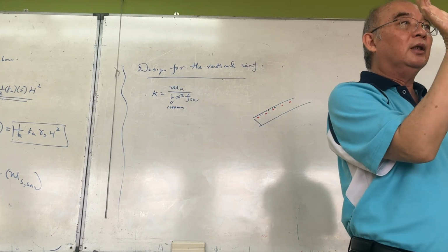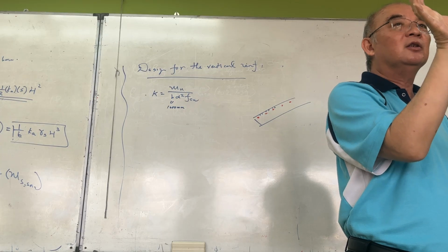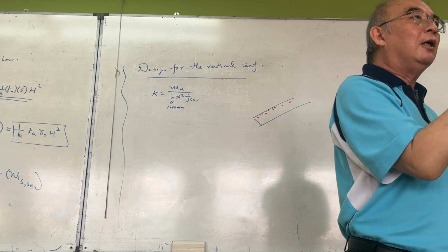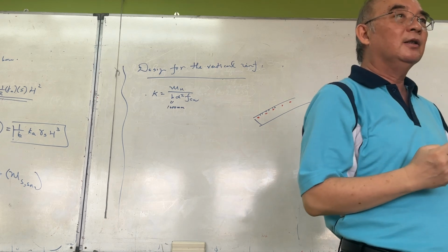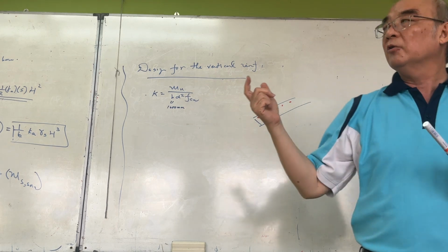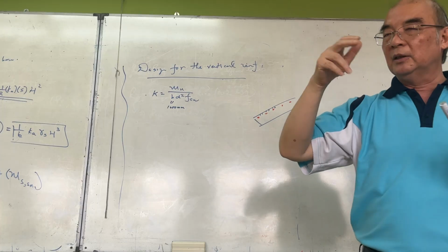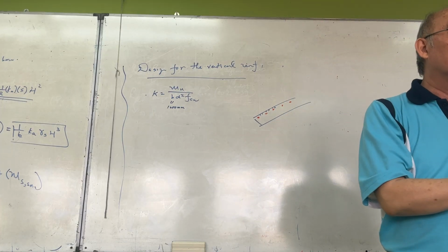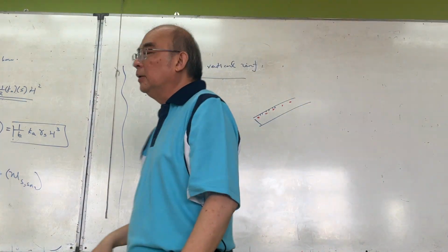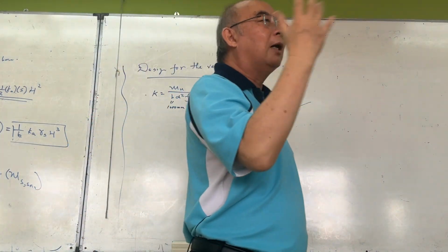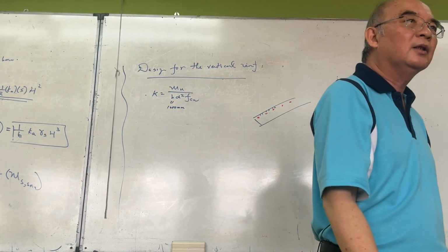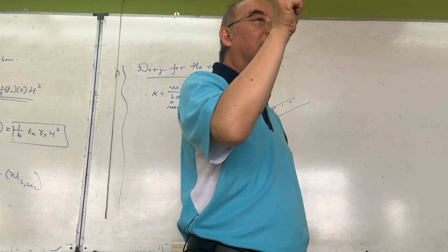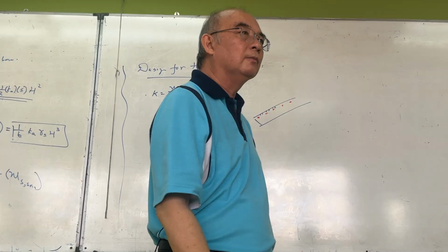TW is the total thickness. So effective thickness is the total thickness minus the concrete cover, because that concrete cover is not effective. Understand? Alright, let's say the concrete cover is 40 plus the bar diameter, but normally D will be given to you. Okay? But when you go out to work, that's how you calculate the D. Understand? Always remember D is the effective depth or effective thickness.